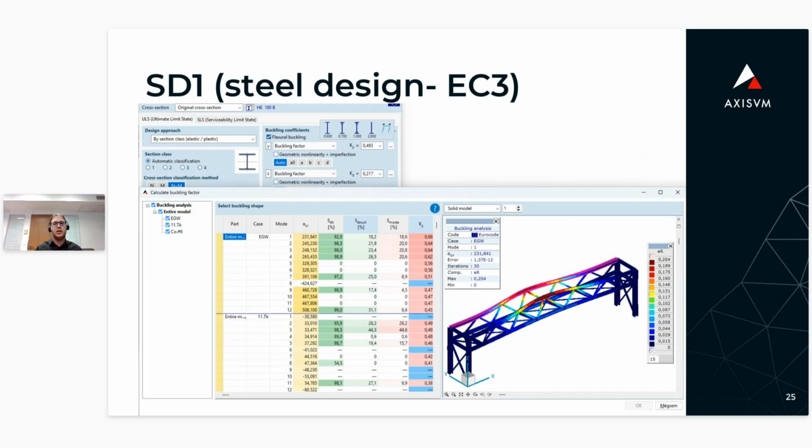The structural sensitivity factor tells you how much the specific design element participates in the buckling shape. If this is low, it means the mode primarily affects other parts of the structure.